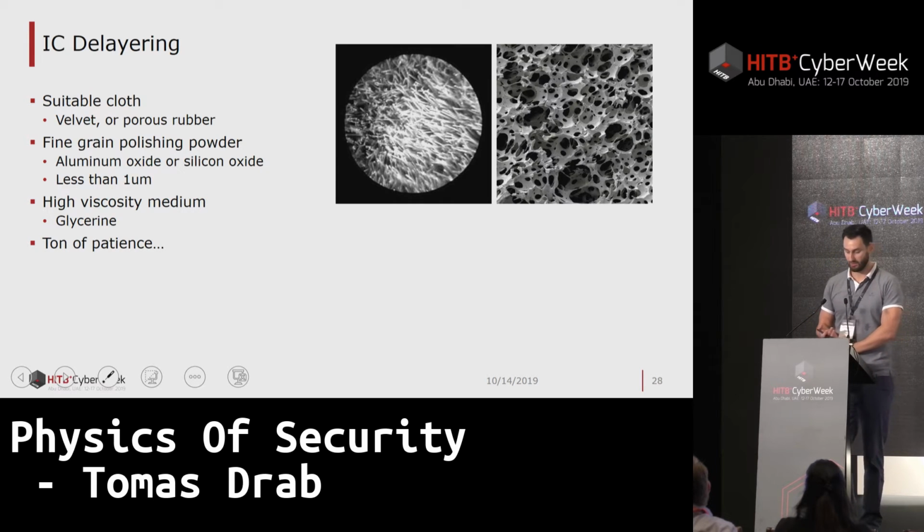Okay, IC delayering. I showed you a really expensive fancy machine which can delayer the chip, but you can actually do it using just your finger. Yeah, this is the old method from before they introduced all these fancy machines.